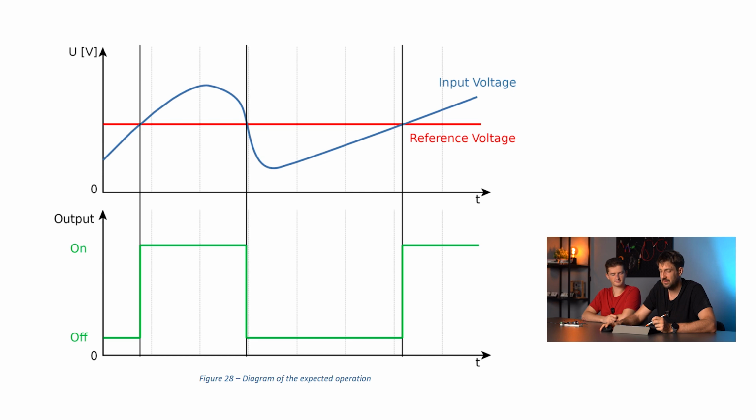In the previously described 12 volt battery tester circuit, the reference voltage is the breakdown voltage of the Zener diodes and the base emitter forward voltage of the transistor, which is 6.6 volts, whereas the input voltage is half the supply voltage. We will examine the relationship of these two voltages with a circuit further on, where the goal will be to decide whether the input voltage is higher or smaller than the reference voltage.